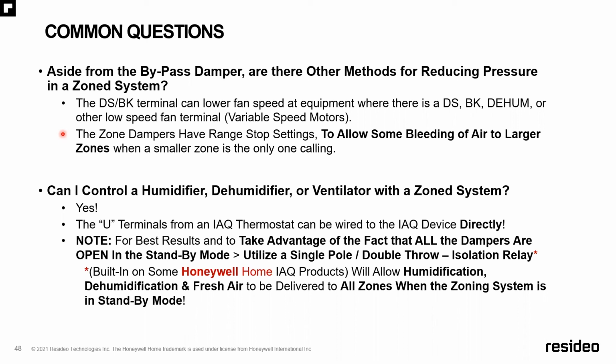Now, a question we often get when you're doing IEQ in a house that has zoning is, can I control a humidifier, dehumidifier, or fresh air ventilation with a zone system? And the answer is yes. It's important to understand that many of our thermostats, for example, our new T10, as well as our 8000 Wi-Fi and our 8000 RedLink, have dry contacts on the sub base that are going to let you control various pieces of equipment, be it a humidifier, dehumidifier,